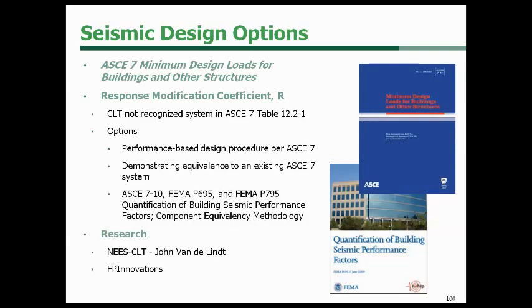Other options you have: performance-based design per ASCE 7, or demonstrating equivalence to an existing ASCE 7 system. Or you can do a FEMA P695 and FEMA P795 analysis, which is something that we are starting, but it's going to be probably a lengthy process, and we're not 100% sure when the project will finish, but we are looking into it.